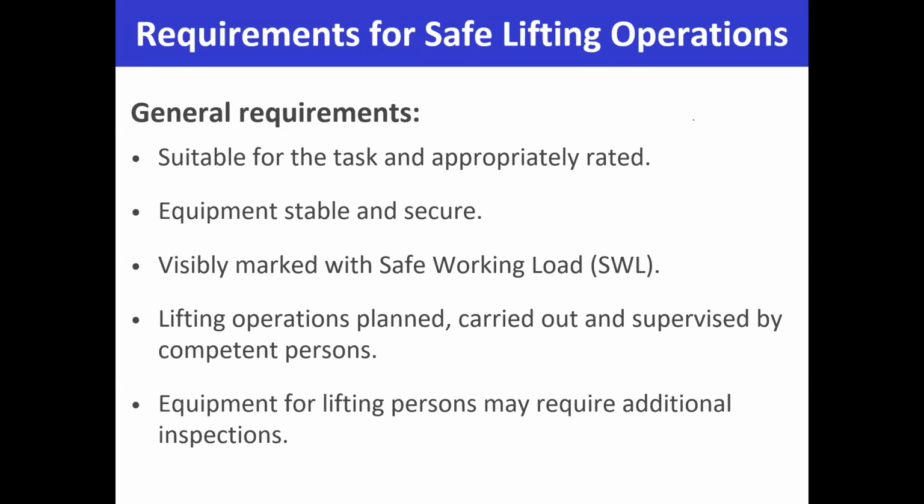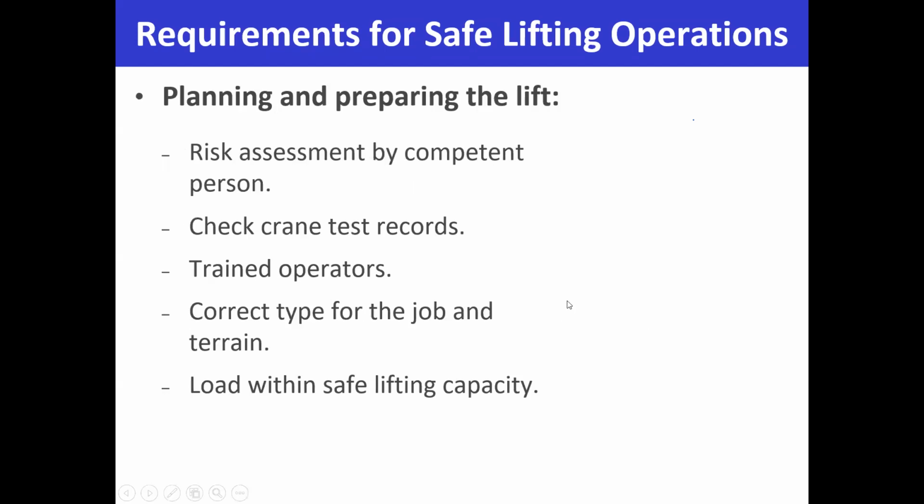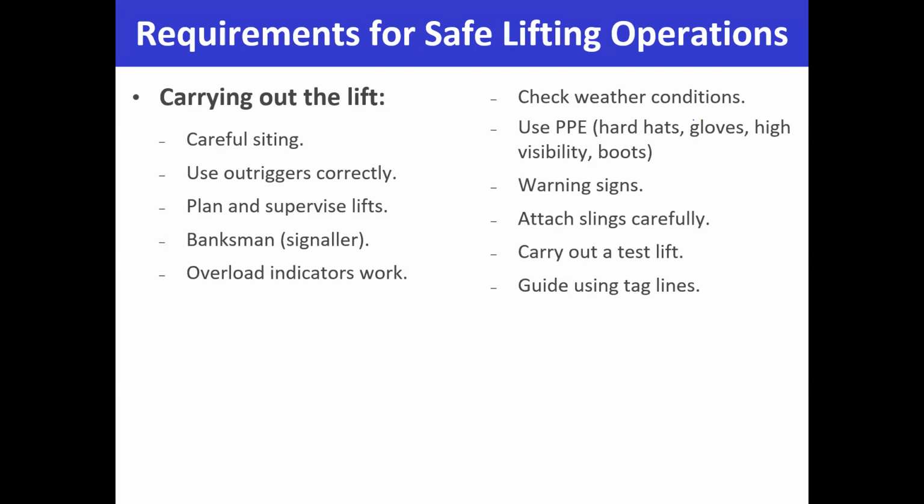Make sure that the safe working load is visibly marked. Lifting operations planned properly and carried out and supervised by a competent person. Equipment for lifting persons may require additional inspection. So these are things you need to consider for lifting activities. You need to plan and prepare the lift, make a risk assessment, check the records, train the operators, and make sure the correct equipment is used for the task.